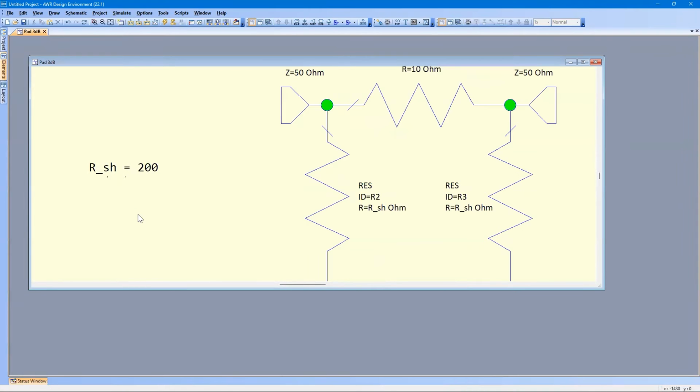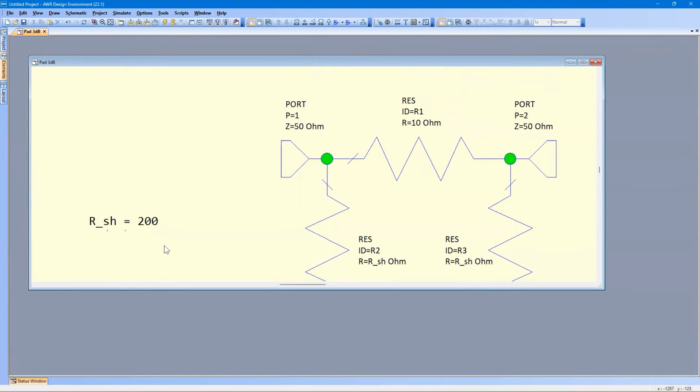And again, that will be adjusted. Now, anytime you deal with variables, it has to be perfectly duplicated. So the case is critical. The underscore has to be there. If this was a lowercase r, you can see these immediately change to red, saying that uppercase R SH doesn't exist. So you have to be careful about your case.